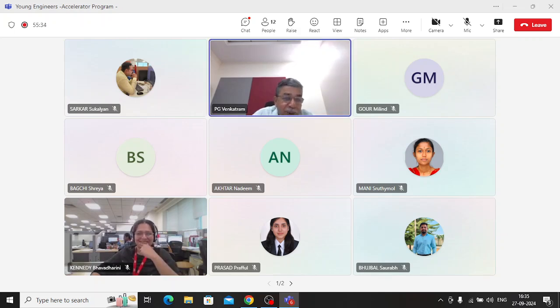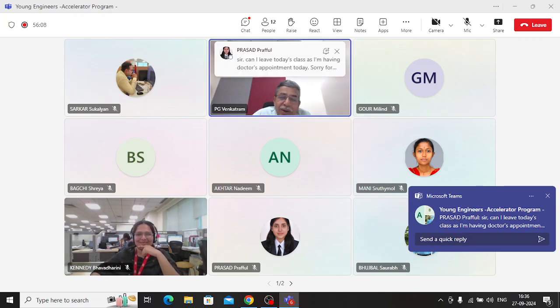Definitely. I don't say no, it will deflect, but will it deflect enough for you to feel the bump? So why do you see the bumps? That's a question. It comes out of the fact that we don't install our expansion joints correctly. We don't do the profile control of our bridge correctly. Next time you travel along a bridge or you see a bridge under construction, you should stop looking at it as a tourist attraction. You should look at it from the eyes of a bridge or infrastructure engineer. What they are doing right, what they are not doing right. You have to.